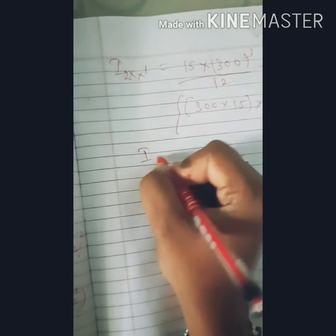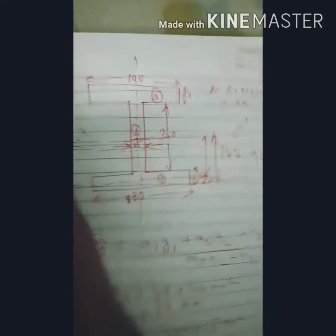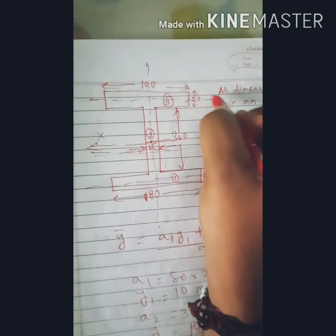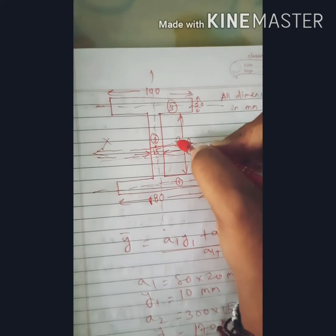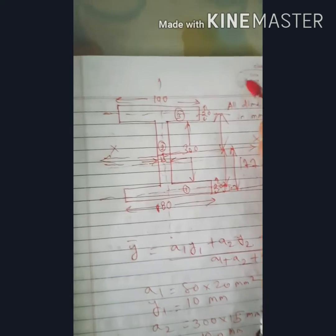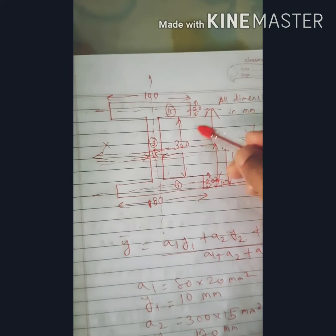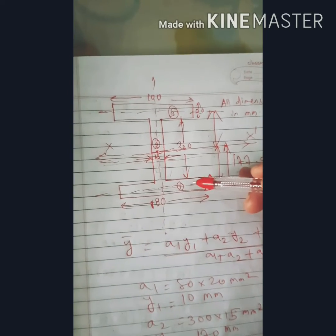Similarly, we will find I3g, the moment of inertia of the third section about its own center of gravity. The third section's CG is at its middle, at 10 mm. The total height is 300 plus 20 plus 20, that is 340 mm.